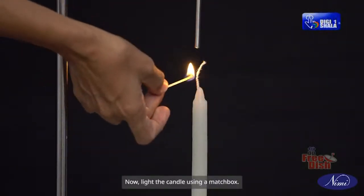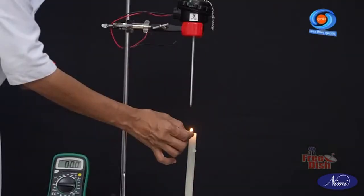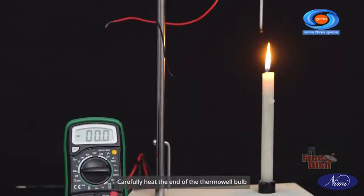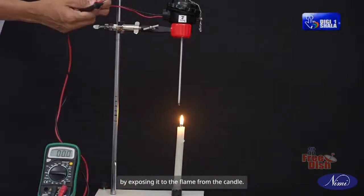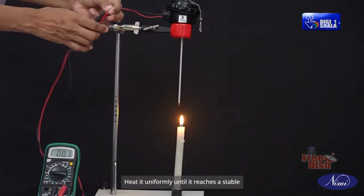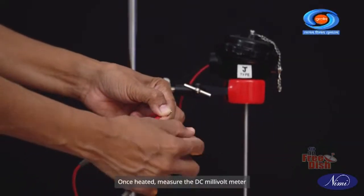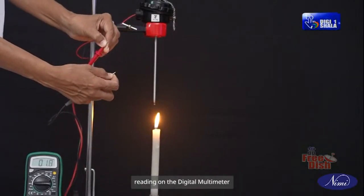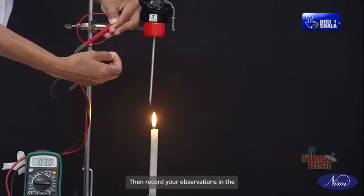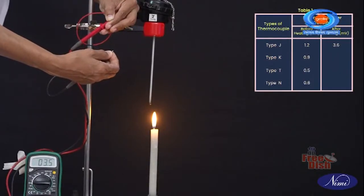Now, light the candle using a matchbox. Carefully heat the end of the thermowell bulb by exposing it to the flame from the candle. Heat it uniformly until it reaches a stable temperature. Once heated, measure the DC millivolt meter reading on the digital multimeter. Then, record your observations in the designated table labeled Table 1.